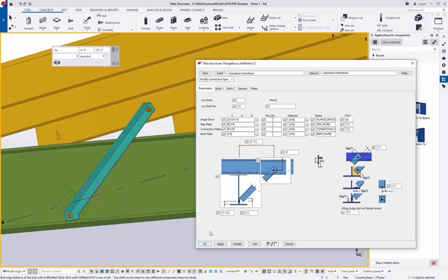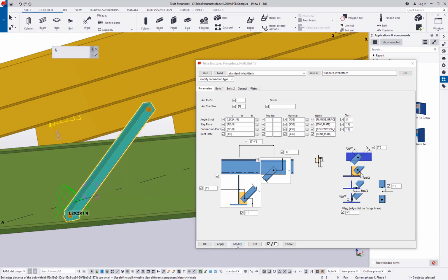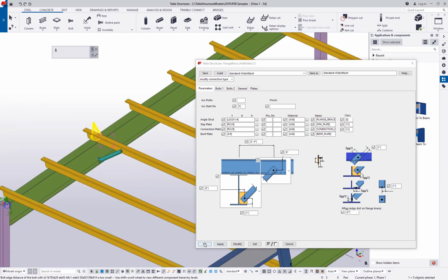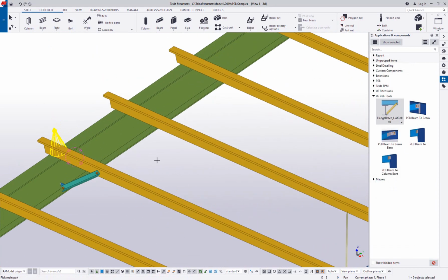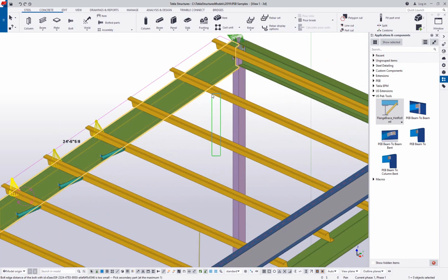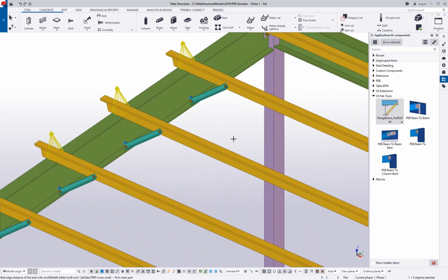And then once you do have an option chosen, let me go ahead and go back to that little stiffener plate that we have down here. We can go ahead and reuse those as many times as you need to on these different purlins. In this case, you can see I'm just sweeping the members so that the connections get applied to all of them at once. So now that we've taken a look at those, let's go ahead and jump back into the main building model that we imported from MBS.